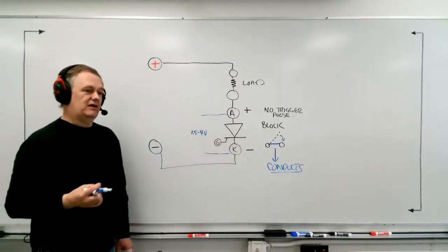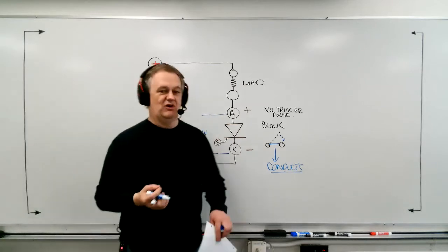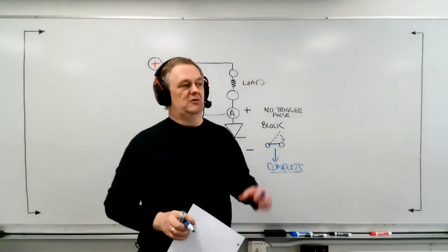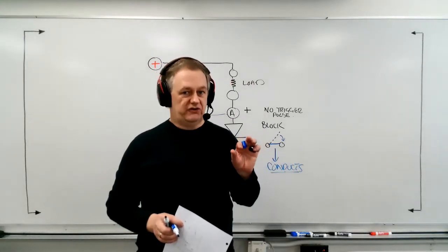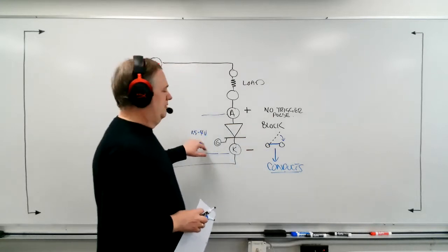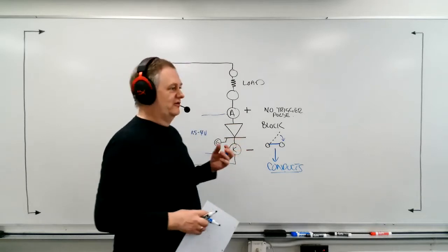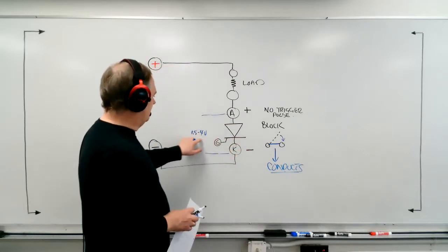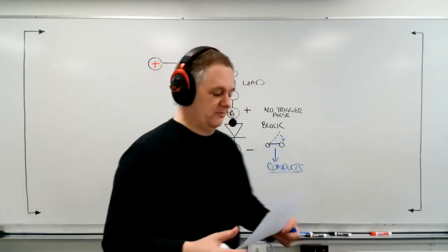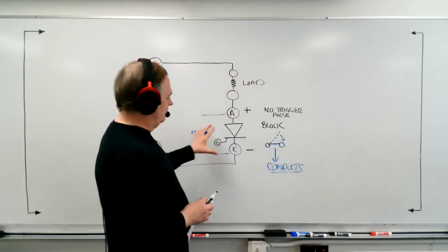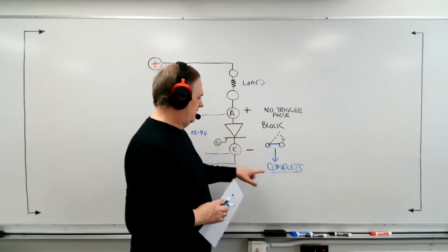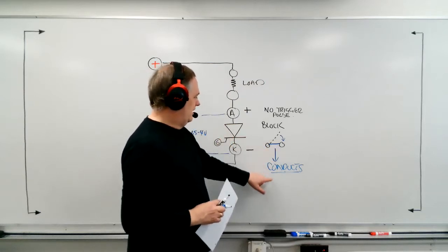And it's not an exact number that you can count on. Like when you're looking at a diode and you say, I know the diode is 0.7 of a volt. Because there are multiple layers here, this voltage drop is literally because of barrier voltages, but there are several junctions in there, so it's a little complex inside. So this level varies, and we'll have to look at the actual spec sheets to know exactly what it is. But in any case, as soon as you trigger the gate with a pulse, the switch will close and it will start to conduct.